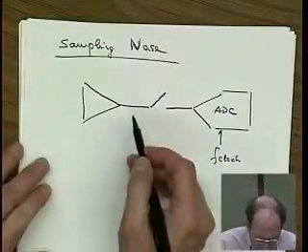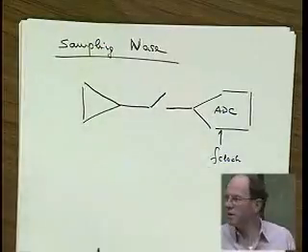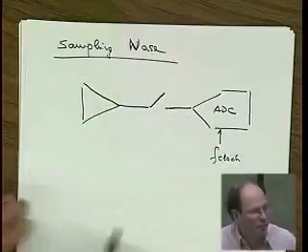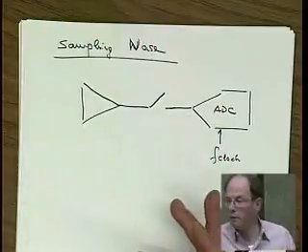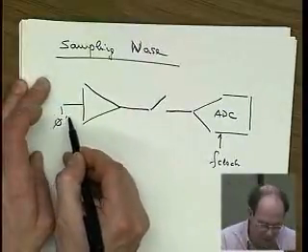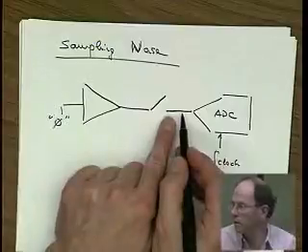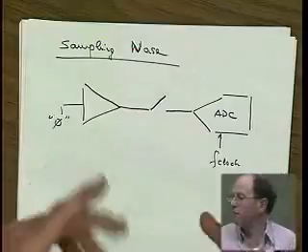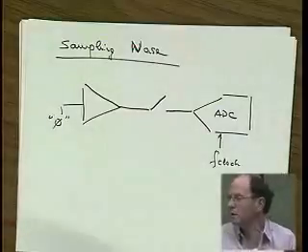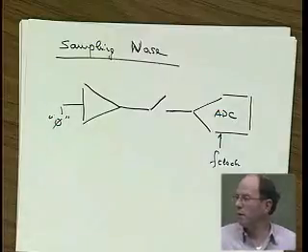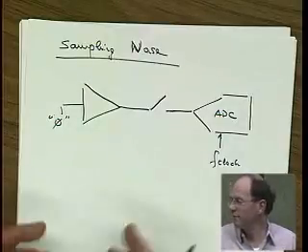The question is, what happens to the noise? The noise is now no longer a signal that changes all the time. Once we've grabbed the sample, we've also grabbed the sample of noise. Even if, let's say here we put in a 0, right? Then we would be grabbing a noise sample. Maybe once we would be getting 1 microvolt, next time minus 2 microvolts, then 0.5 microvolts, whatever, right? We'd get random noise samples. What are they going to be, or what is their variance going to be, right?